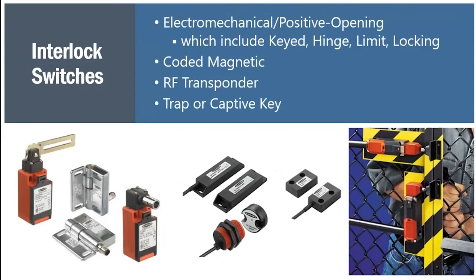So, for example, let's say you've got a laser drilling machine that creates a metal vapor with some toxic metals in it, or a robot that does painting with solvent paint. Before you gain access to that enclosure, you can tie it to a time delay to allow the ventilation system to remove that chemical hazard before you gain access.